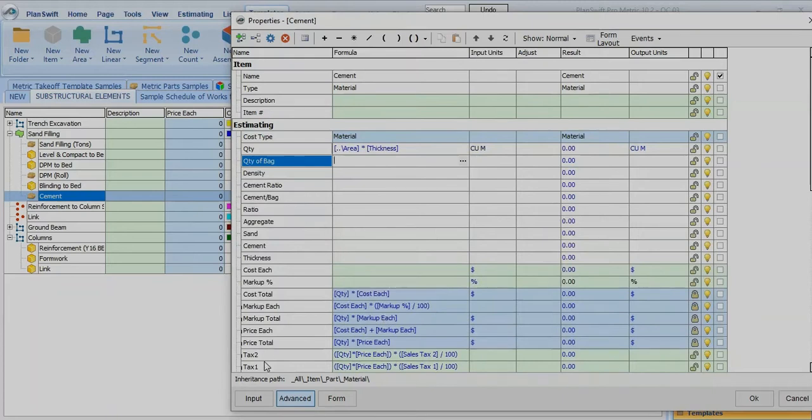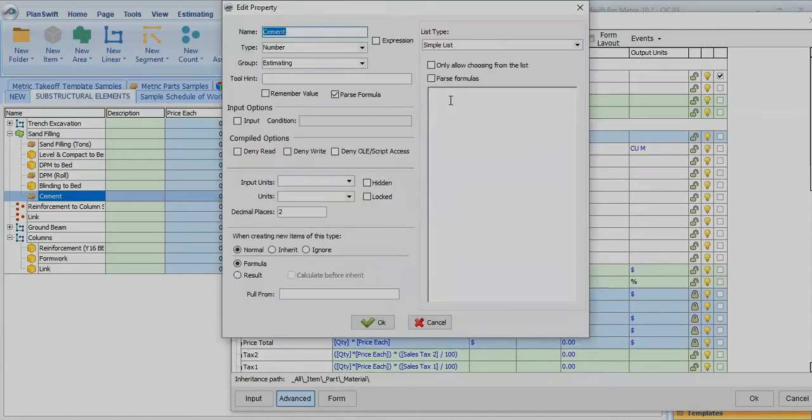So having done all this, we want to assume the ratio of concrete for blinding. So let us assume 1:3:6. So we know that ratio of cement in this regard is 1, sand is 3, while aggregate is 6. So let me predefine cement ratio.